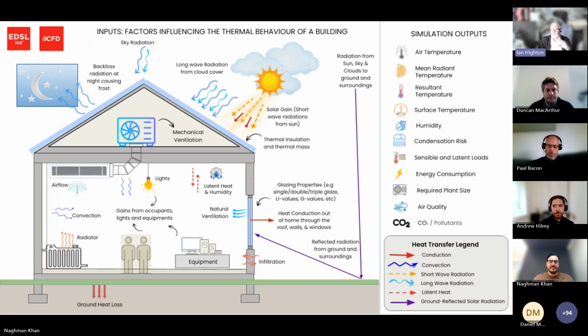It's trying to make sure you've got the temperatures set correctly so that all of the heat fluxes balance out, and you've got conservation of thermal energy, which sounds a casual way. I just say, oh yes, it's going to work out that equilibrium point for all of these surfaces in all of these zones in these massive, great, 4,000, 2,000 zone models. Those are the worst. That's obviously where it gets the trickiest. Plus, of course, you've got the airflow networks bouncing around in there at the same time. So yeah, it's a non-trivial task.